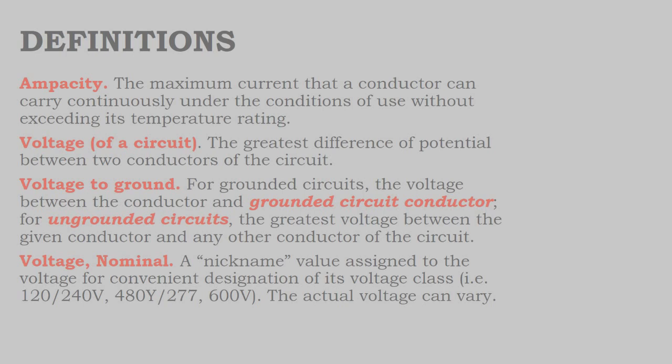You have a 48-volt battery bank, but for certain batteries like flooded lead acid batteries, you might have a maintenance feature where you drive the battery bank voltage up beyond 48 volts into the 50 or 55 volt range. The battery may be designed to take 60 volts, but its normal operating voltage is 48 volts, and that would be the nominal voltage. But generally, you don't design around the nominal voltage. Generally, you are designing around the maximum circuit voltage.